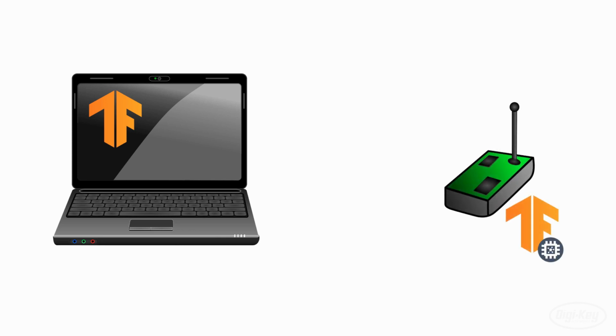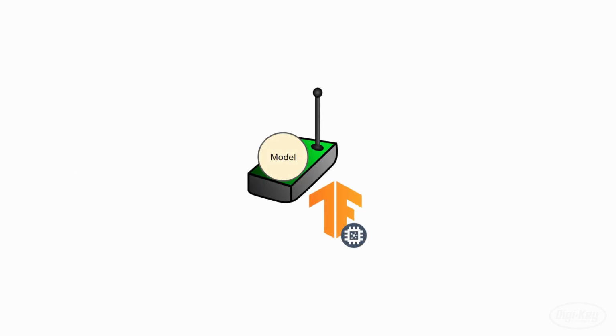Since microcontrollers are usually very limited in resources, you generally don't want to train a machine learning model on them. So a basic workflow is to train a model using full TensorFlow on your computer or some other server. You'll then convert that model into a TensorFlow Lite flat buffer file. This .tflite file works with regular TensorFlow Lite, but you'll need to convert it to an array in your language of choice for microcontrollers. For us, we'll create a C array and then transfer that over to our microcontroller so it gets loaded into memory. With the TensorFlow Lite for Microcontrollers library, we can now perform inference using our model on our microcontroller.